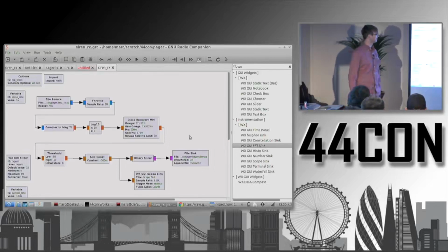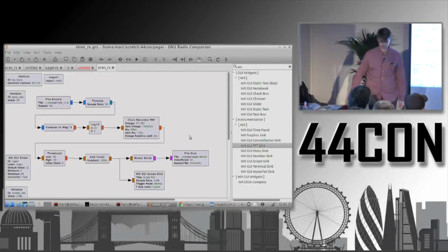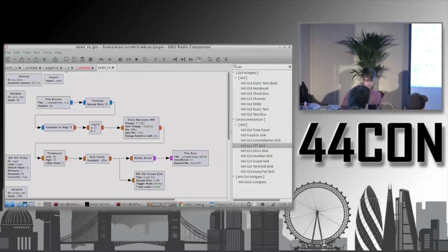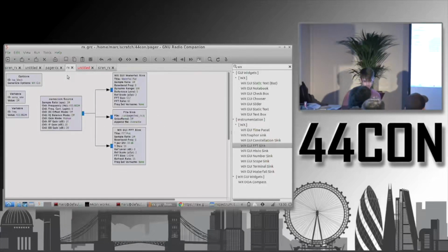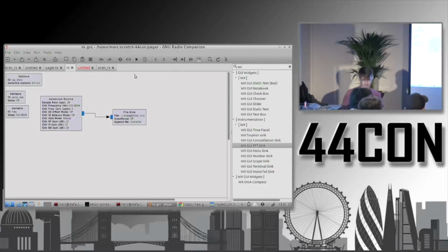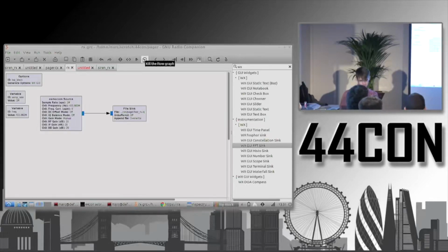Maybe we can do this briefly, because we're pushing right up on the end of our time here. Maybe we can set up 2 different pagers, capture them, and then look at them in URH and visualize how we can start to see differences in the capture. That's a good point. So we'll do a quick capture with 2 different pagers, run that through URH, and we'll see the 2 different payloads. Generating data with known different inputs is a pretty good way to start to figure out what the packet format is, because then we can make some assumptions about what parts of the packet change when different input happens.